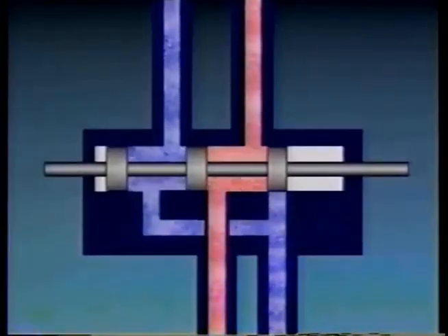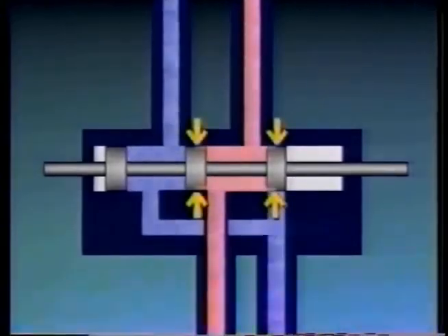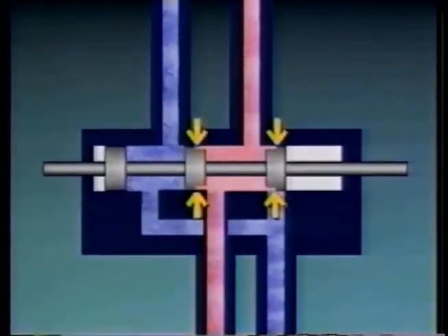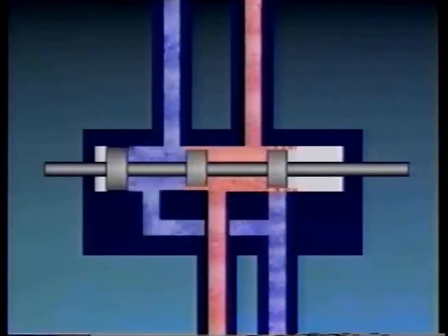Viscosity is also important because the fluid helps reduce leaking between close-fitting parts. If the viscosity is too low, the component will pass too much fluid through these clearances and flow through the remainder of the system will be reduced. In addition, as the fluid passes through these narrow clearances, more heat will be created by friction.